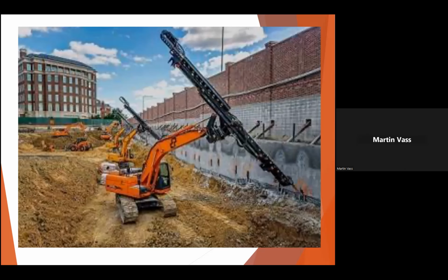Obviously, before you put the anchors in, you must go to the adjacent property, to the engineers, whoever is adjacent to you, and say this is what you're going to do, get permission to put those anchors in the ground, and then reach an agreement on how long before you have to remove them.